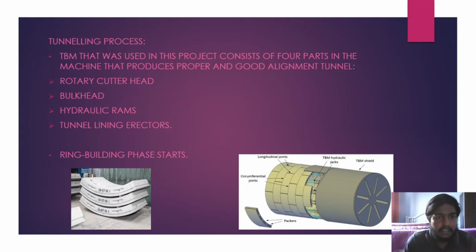There are several criteria that have been taken into consideration in this method, as the method is not a set of specific excavation and support techniques. First one is mobilization of the strength of the rock mass. Second is shotcrete protection. The third is measurements. Fourth is flexibility. Fifth is closing the invert. Sixth is constructional arrangement. Seven is rock mass classification determining support measures.